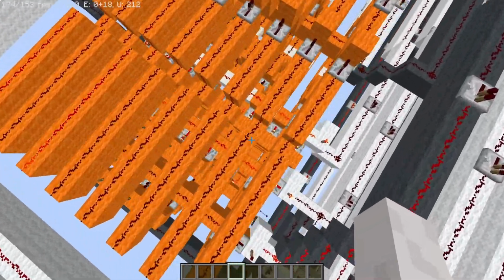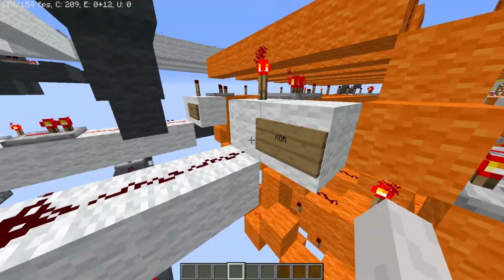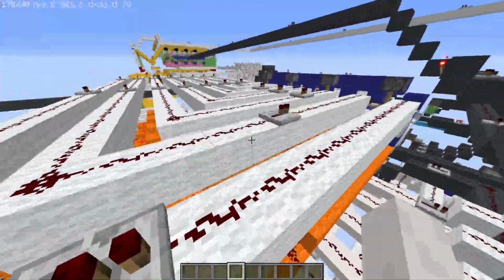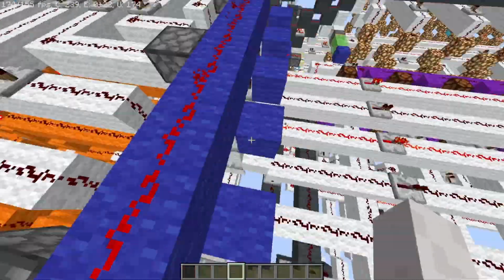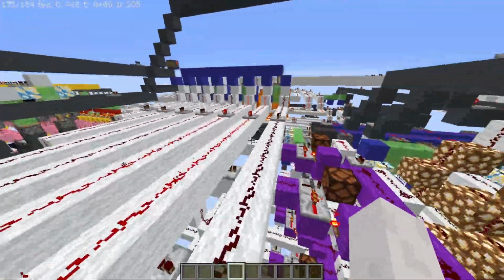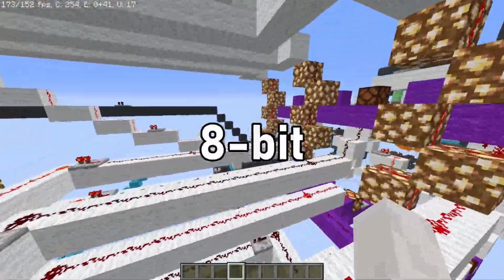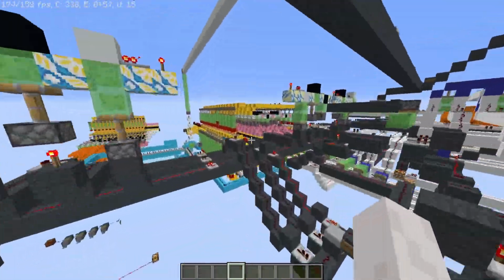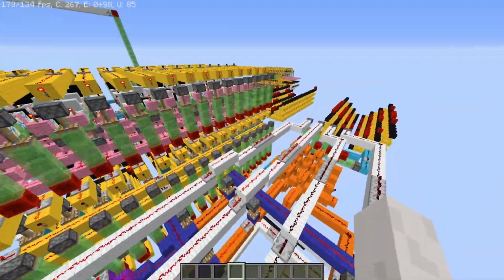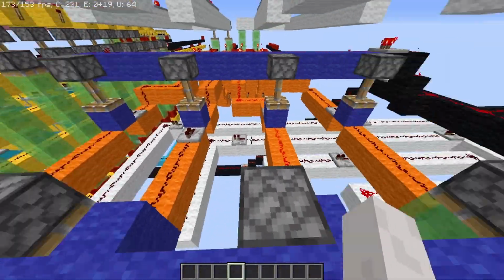This orange circuit here is the almighty ALU. So we've got AND, we've got XOR, I think that one's add, yup. We've got a NOT gate conditional on the end of that. The blue things are buffers that kind of either allow the signal to pass through 8 wide or not. As you may have seen, it is an 8-bit CPU, 8-bit registers, 8-bit slots in memory. However, since the program memory is only 16 bytes, the program counter is only 4 bits, because that's all you need. So here's the program counter over here.